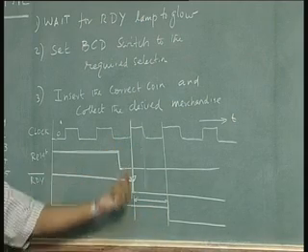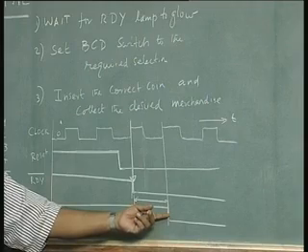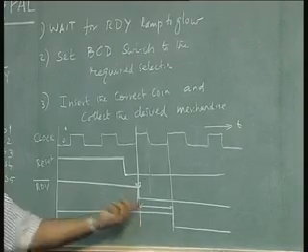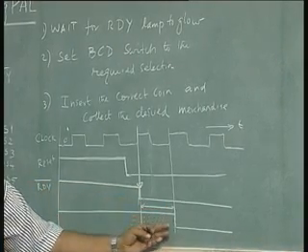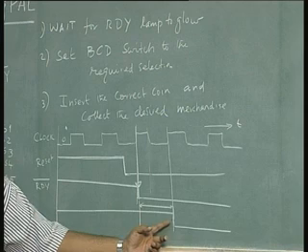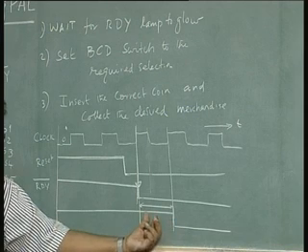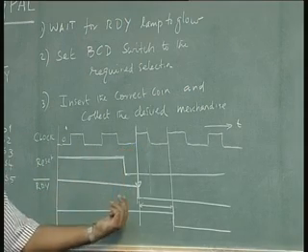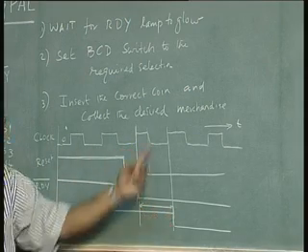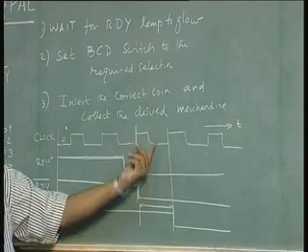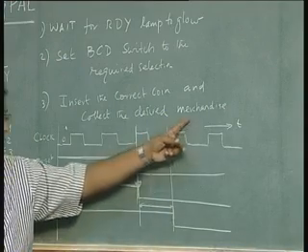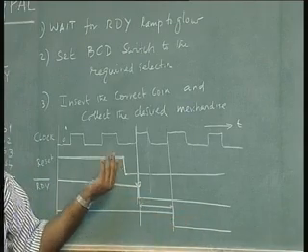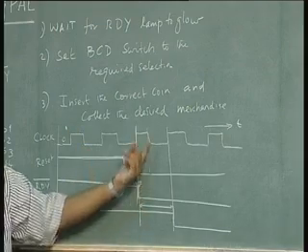It can be part of a clock cycle, but then action can always happen in a synchronous logic. In a synchronous design, the action can always take place along the clock edge. So, the delay from the ready signal to the time the merchandise is dispensed will depend on the circuitry. If it is less than a clock cycle period, the action will take place at the next clock edge. If it is more than a clock period, let us say somewhere here it takes, then it will go here. So, I am just giving an estimate. We do not know the logic inside. So, I am assuming it is going to take 1 clock cycle.